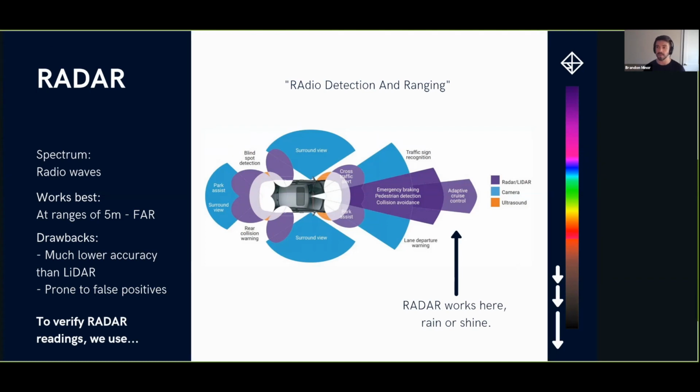Radar and sonar both, this is what you use for weather images, right? It's huge. You can do a lot of distance, but it has much lower accuracy than LiDAR because of its physical properties. It's a much longer wavelength. It can't hit the fidelity that LiDAR can as far as points. So what you see in radar is basically the heading of an object. You see this object is going this fast at me, and I know that for certain, but what I don't know for certain is the position of that object relative to me. And so the mathematics gets much more complicated because you're trying to infer this over and over at a long distance.